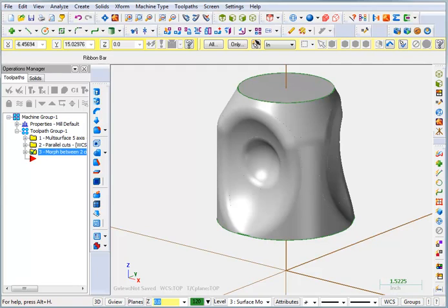This might look like a good example for a 5-axis part, but more than likely you could machine this part a little more efficiently by doing it as 3-axis surface machining. So leaving the part mounted as it is right now, we could actually do a completely different process.